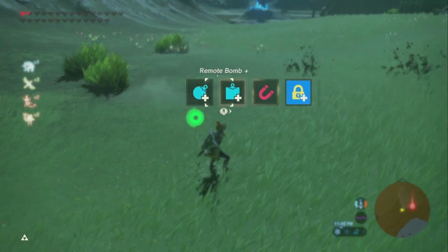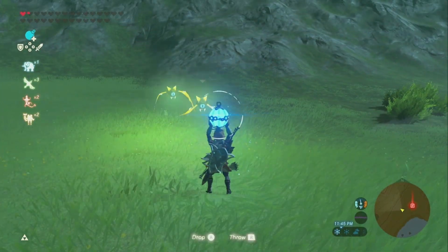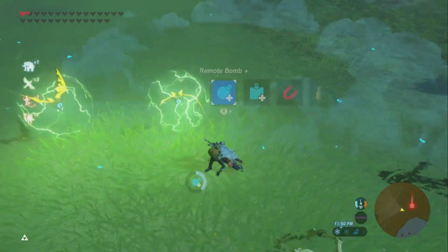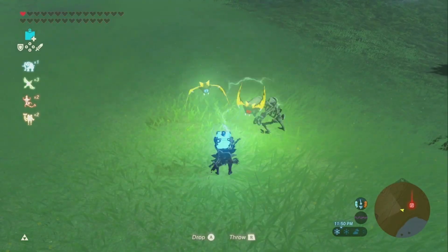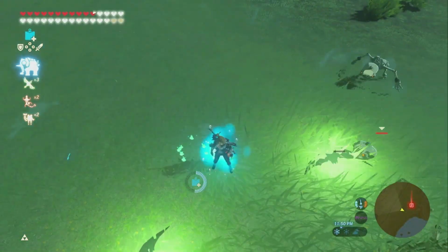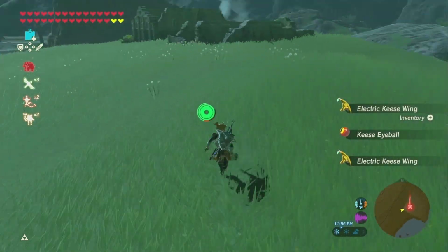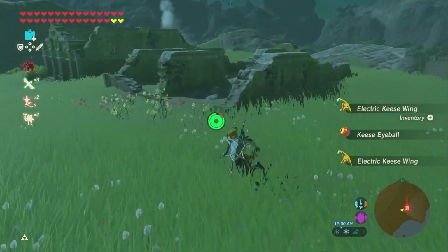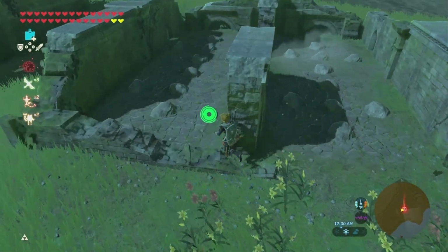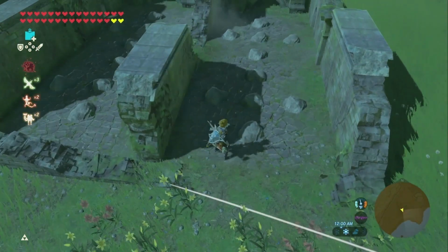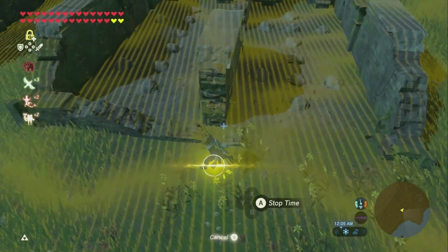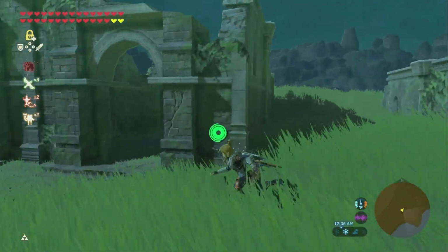Implications. A burner cover or heat rollout shield will allow the burner to get dirty. It will also allow flames to roll out of the burner in a backdrafting situation. This can be a fire hazard and may damage the controls. If the burner cover or heat rollout shield are damaged, they won't be able to do their job. If one of these is rusted, it probably is not easy to operate, and may not be able to perform